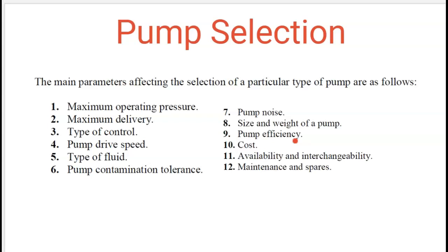The other one is suitability. Is that available? Can I change it with another system? Is there compatibility as well? If there is no compatibility of that pump for a specific system, we are not going to put that pump in place, because it's simply not going to work. Then we also look at maintenance and spares. Can we maintain the pump?